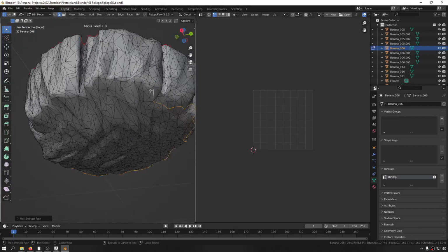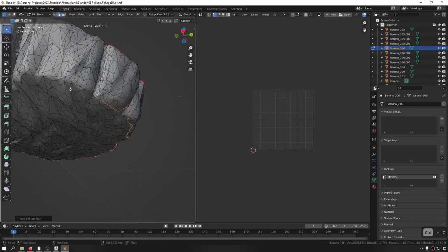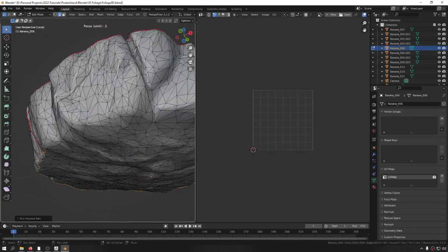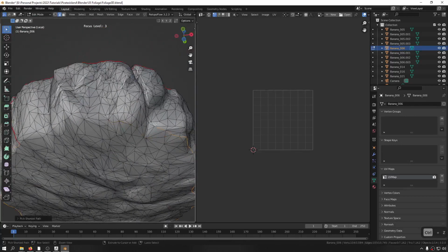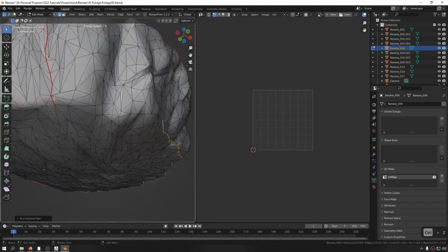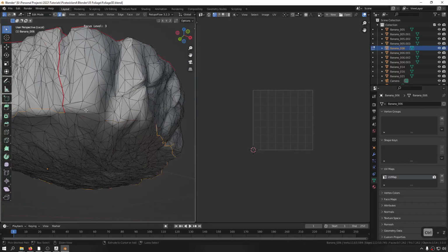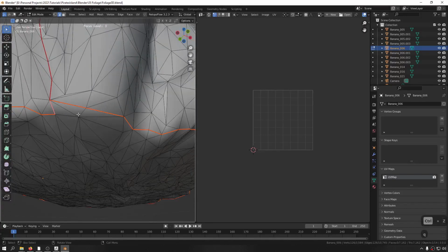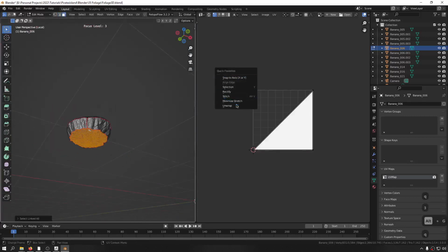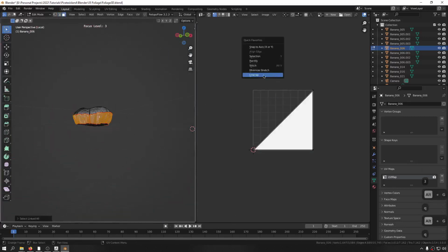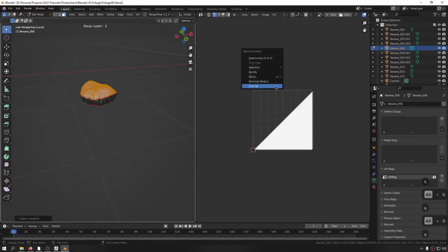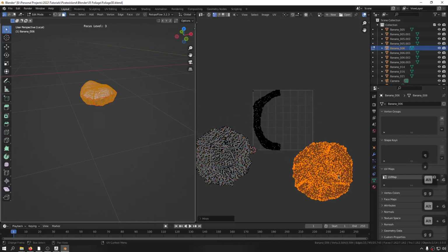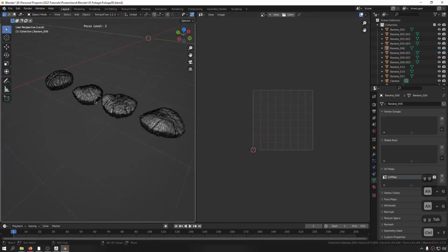We really do not have to create a lot of UVs, and UV is normally a daunting task to do. But this one is so natural, it makes UV creation a bliss really. Go from here and from here to here, okay? Mark seam, and now select this, unwrap, select this, unwrap, and select this and unwrap. Okay, we have 3 pieces right over here. Let's go for the next one.